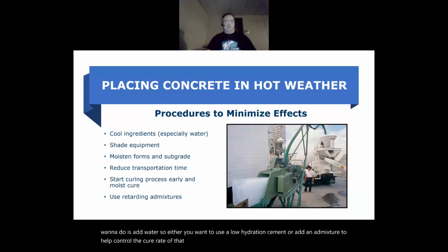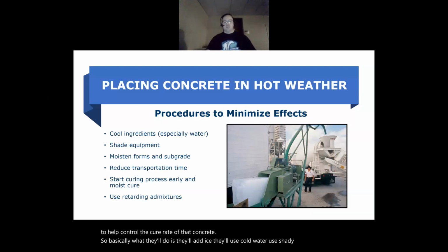Basically, they'll add ice, use cold water, use shady equipment, and again, like I said, retarding admixtures.